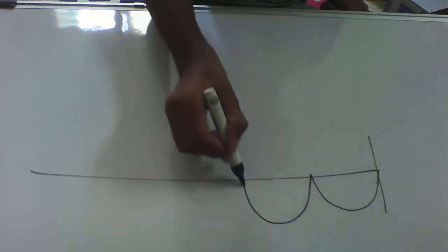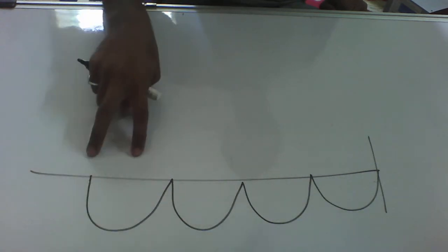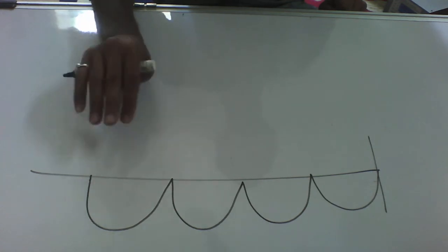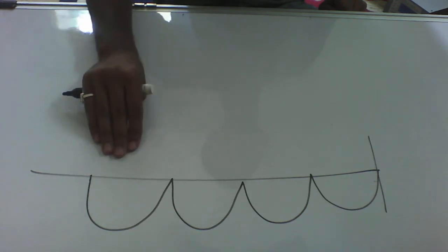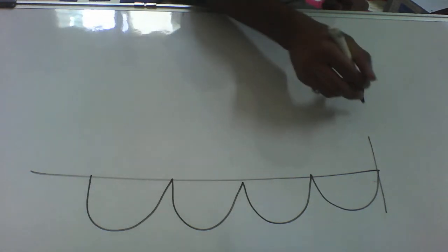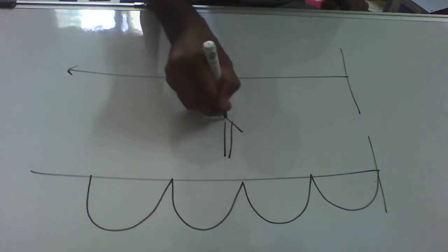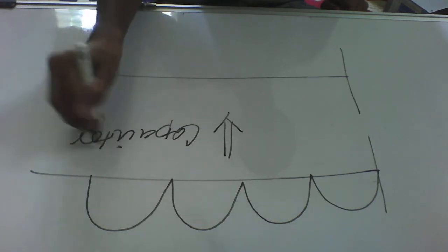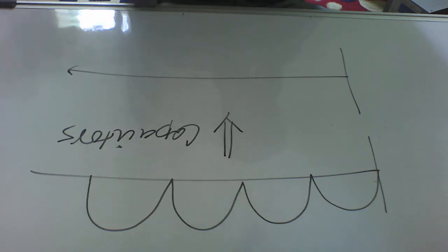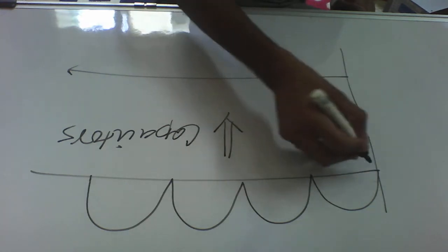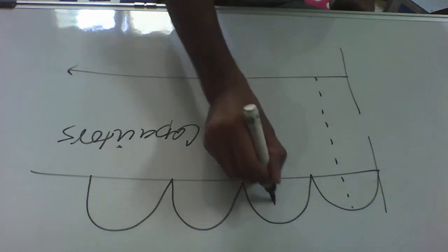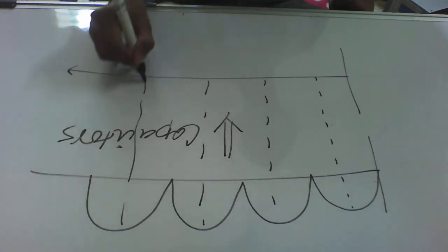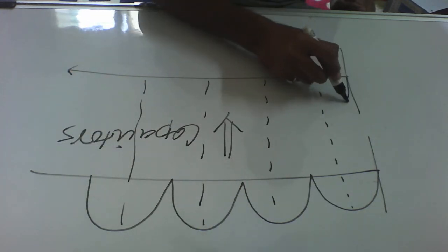So let us consider a pulsating supply which we got from the full wave rectifier. Now we have to convert this pulsating supply into a constant DC. So how can we do it? Pass this through a capacitor. The basic task of the capacitor is to create charging and discharging. During the upper threshold, when the supply reaches the upper threshold, the capacitor will start charging.